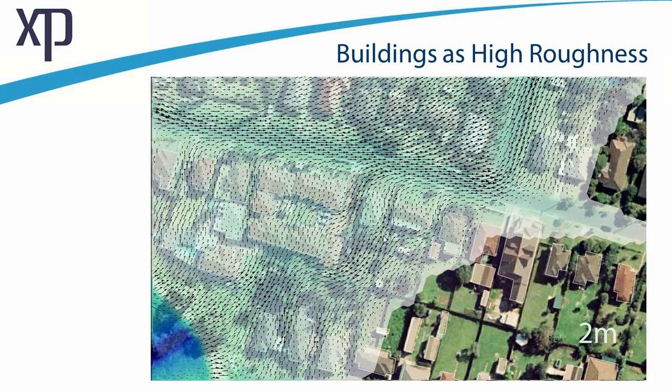So just on the pros and cons of the different building approaches, inactive buildings are very tempting, not necessarily a common way, but people would like to do it that way. But the important thing to recognize is that you do not include the storage effects. And your grid resolution has to be fine enough that you can represent the flow patterns between the buildings and other structures.